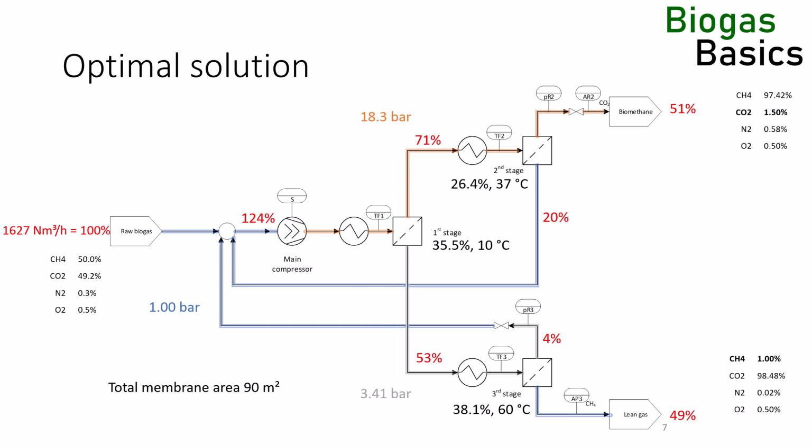The optimal parameter vector Xi depends on the biogas composition, target gas qualities, total membrane area, and other process modifications. The optimum shown here is for one set of parameters. It will vary with different total membrane areas and required gas qualities. The fmincon solver only finds local optima; other global optima could be out there. But now that we have the model, we can run a couple of sensitivity studies to see the impact of total membrane area, target gas qualities, and other process modifications.